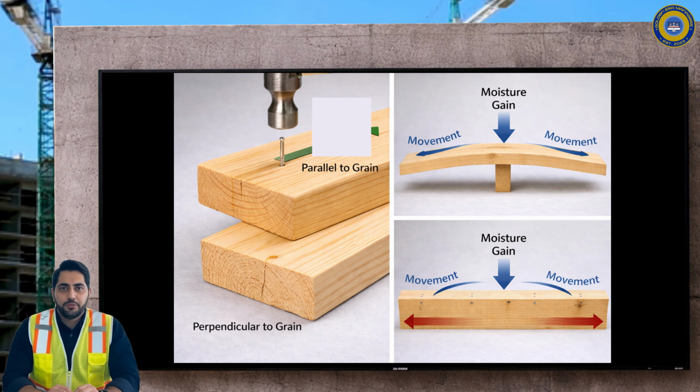Because solid wood comes from a single piece of timber, it behaves differently in different directions. Engineers describe this as anisotropic behavior. In practical terms, solid wood is strongest parallel to the grain, weaker perpendicular to the grain, and far more sensitive to restraint and moisture than most people expect. It does not expand and contract evenly. It moves differently depending on orientation, exposure, and how it is fastened into an assembly.